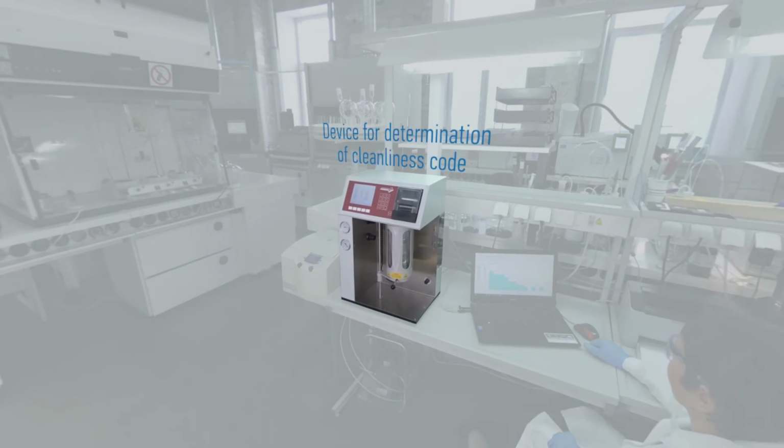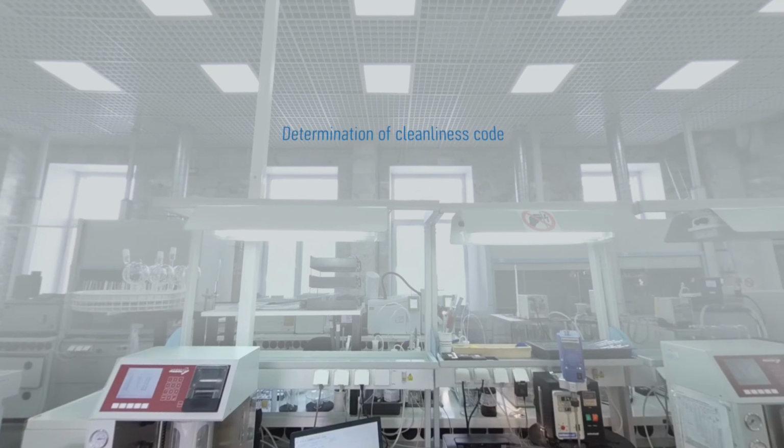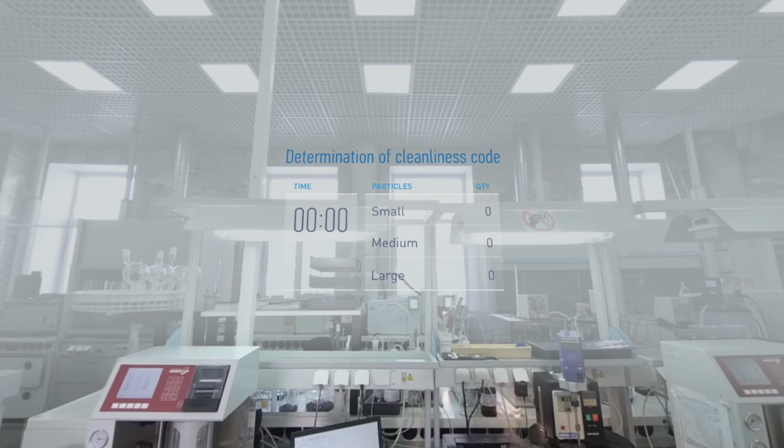Cleanliness code is one of the most important indicators for hydraulic oils. Gaps between parts in hydraulic systems are very small, and they're extremely sensitive to contamination. Therefore, hydraulic oils need thorough filtering during manufacture and operation. To determine the cleanliness code, the oil is passed through a counter where laser analysis is used on the sample. The size and amount of contamination and opaque particles are determined. Manually, this analysis would take more than 1 hour, but now only 10 minutes is needed for it.